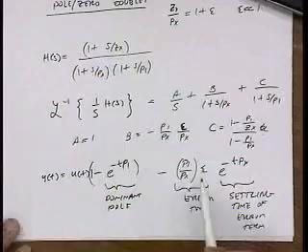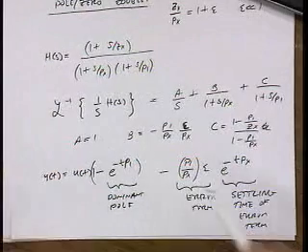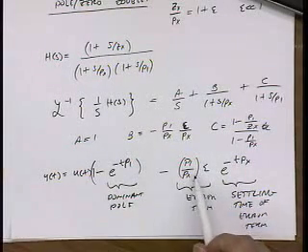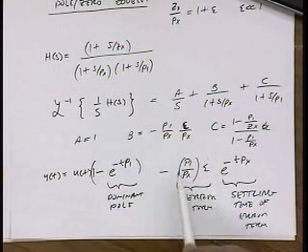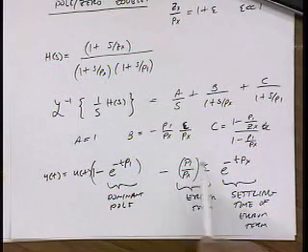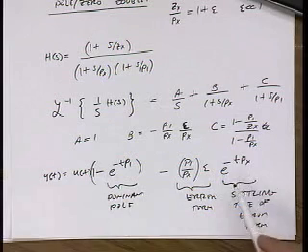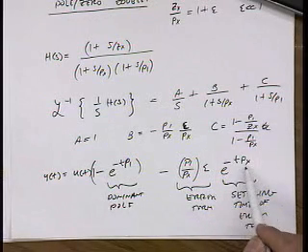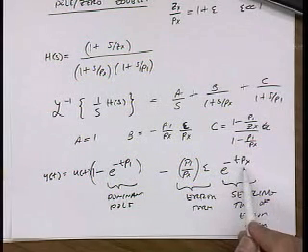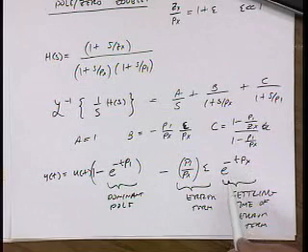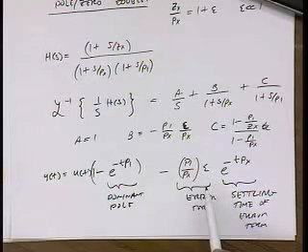And so, you know, this is going to have some kind of magnitude. Let's say, just take an example, P1 over Px works out to be 10. And let's say epsilon is 1%. Then this is already 10%. So you can see that this term could introduce a 10% error in our settling time. And the time constant, just the way I picked it, I took the case where it's slower. So this time constant is then 10 times slower than this time constant. So clearly, the settling time is going to be determined by this pole zero doublet.